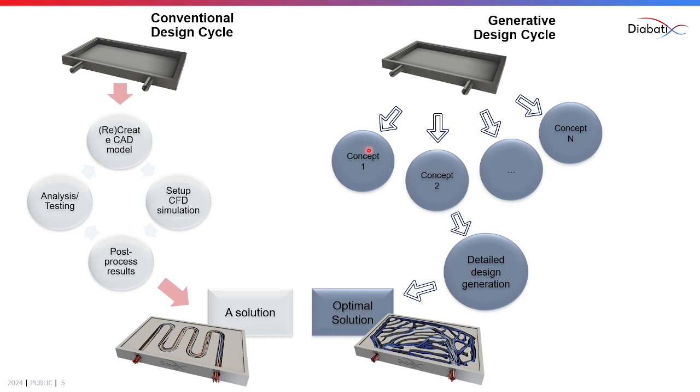You get great insight into what design change affects the performance and how far the performance is from the thermal requirements. For example, if the performance is way above the thermal requirements, then you know that the chip layout, for example, is not sufficient and you have to redesign it. If the thermal performance is way below the requirements, it means that you have a bit of room to play with. For example, that you can condense everything or package it in a tighter space. And if you're right around the edge, then of course you know you're on the edge of the performance, so don't make too many design changes anymore.